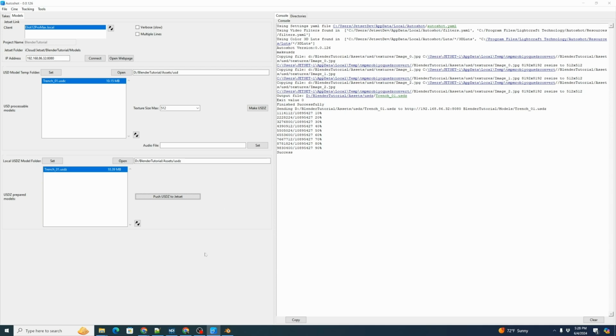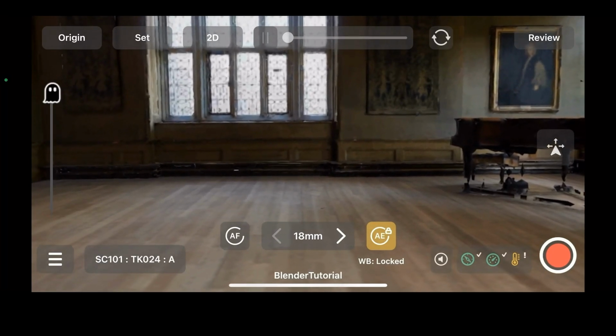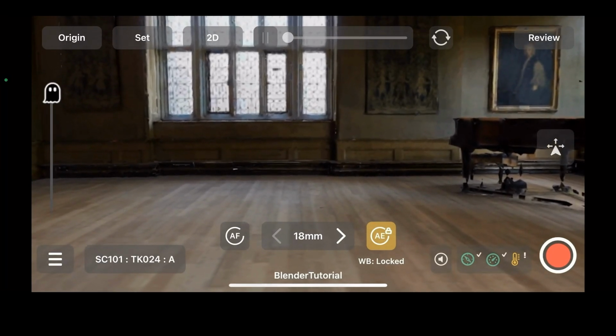And in general, you want to keep the model size modest. So this iPhone 12 Pro Max can handle models up to around 100, 150 megabytes. Sometimes it'll start to have some frame drop issues when it gets hot and when it has a big model. So I've decimated the model and cut down the textures a bit to make sure it fits. So if you're seeing a lot of dropped frames in your models, just decimate and cut down the textures, and you should be fine.